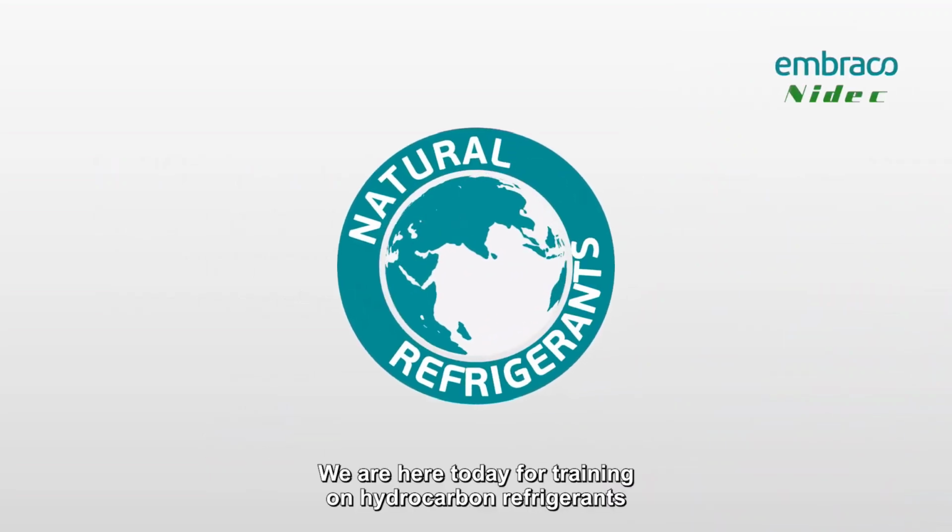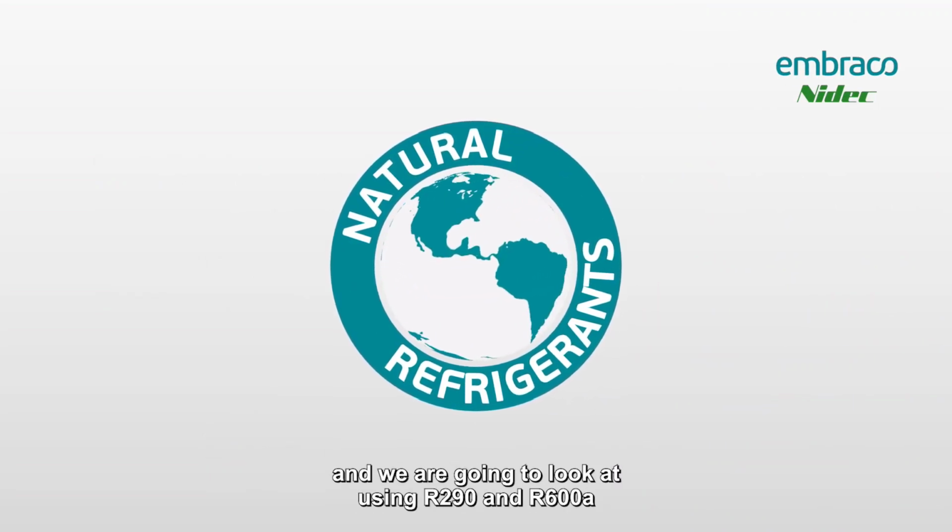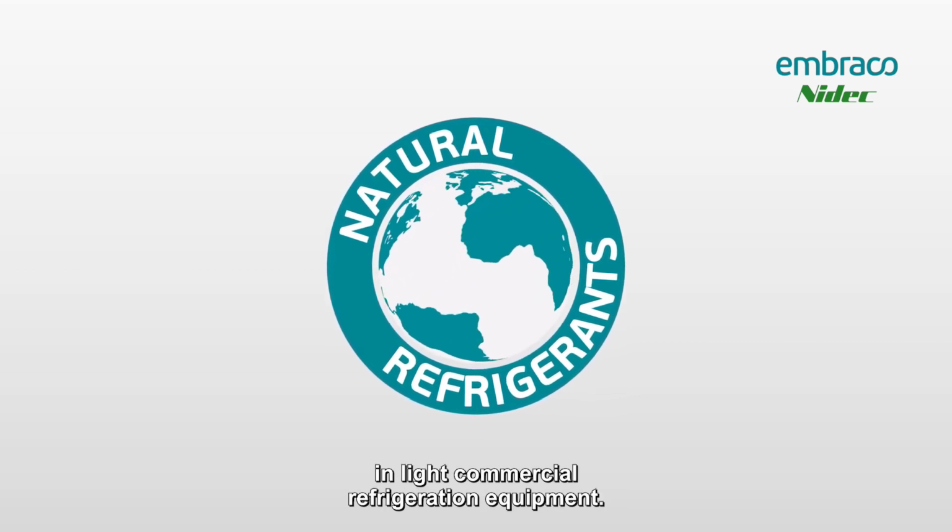And we are here today for training on hydrocarbon refrigerants. And we're going to look at using R290 and R600a in light commercial refrigeration equipment.